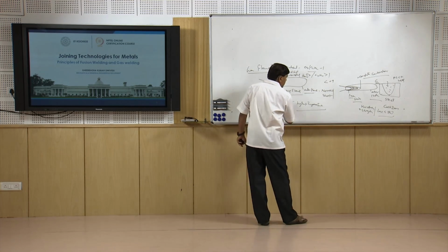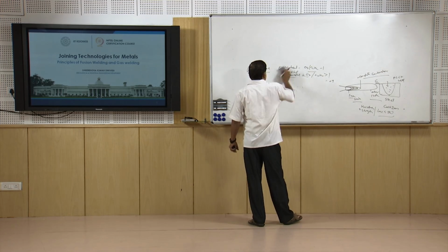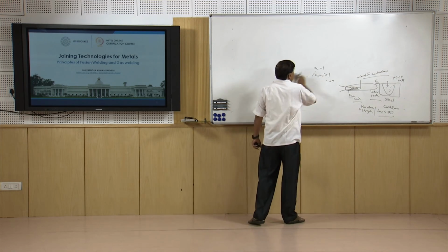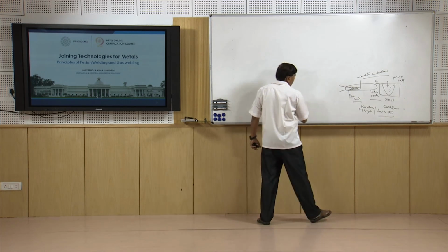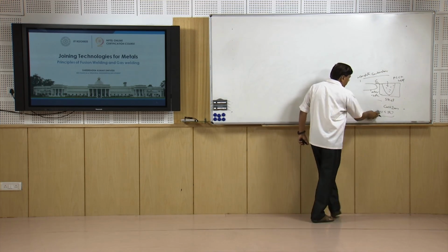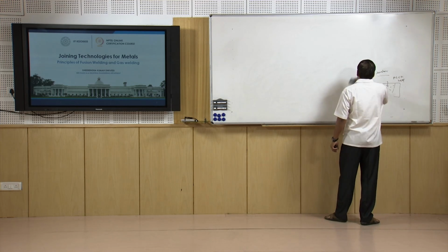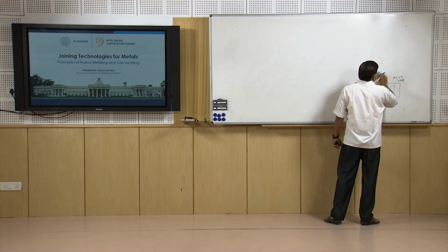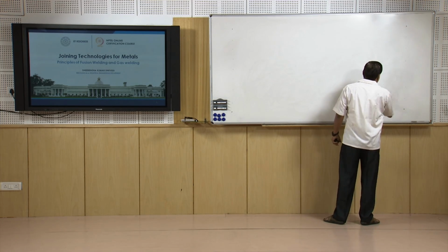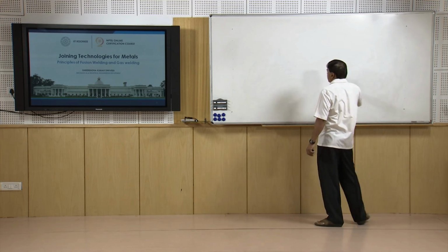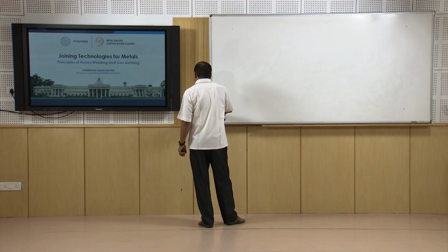So, this is about the different types of flames which are formed in case of gas welding. It is preferred to use the neutral flame, where complete combustion of the acetylene and the oxygen takes place during the welding. Sometimes when high resistance and high hardness is required, low carbon steels can be welded using the carburizing flame also.